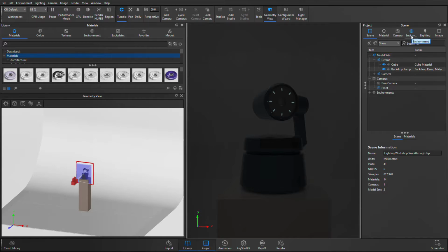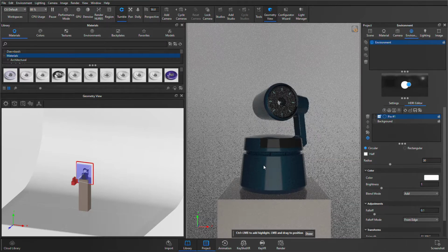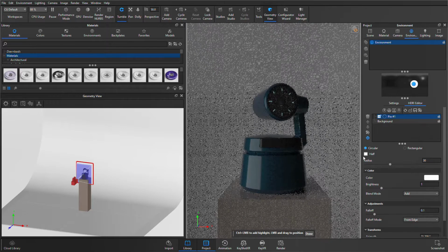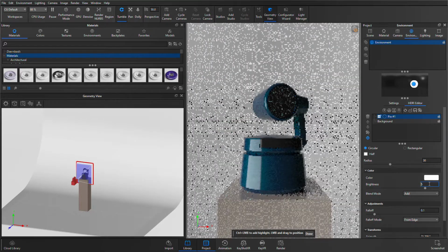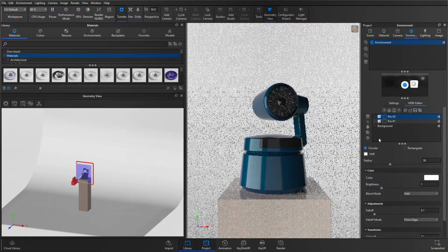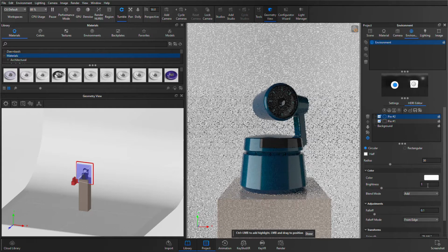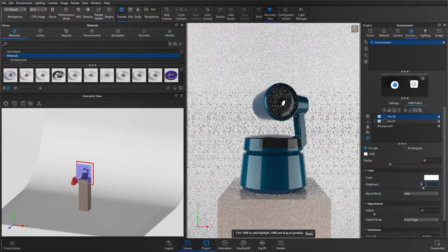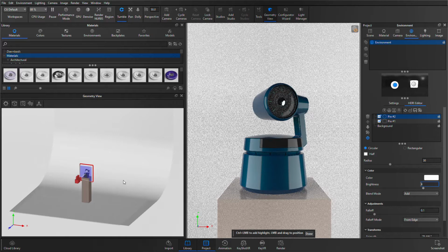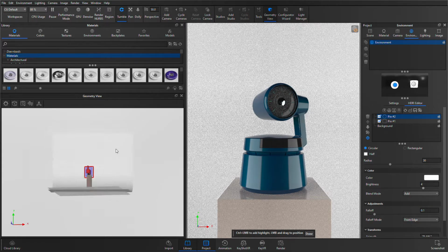So the reason I use physical lights instead of say HDRI is because if I add a couple of pins in here, even though it's really quick to get some good results, I can just up that brightness, turn it to say a rectangle, add another pin, use the crosshairs highlight tool, and already get something half decent. You'll see that I've got the geometry view open as well, which you can open with O on the keyboard, and there's no visual representation of the light.